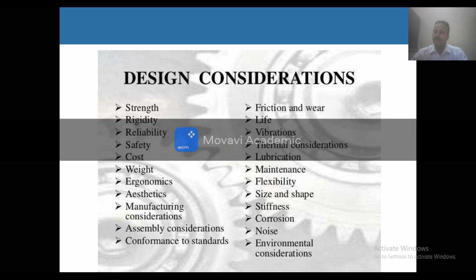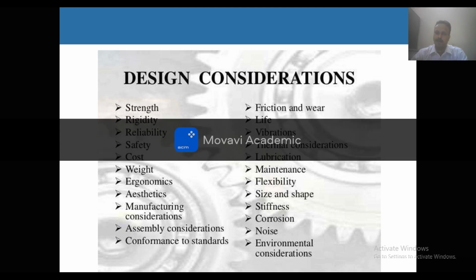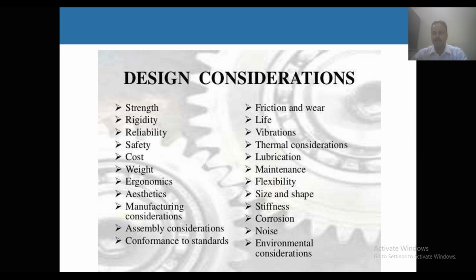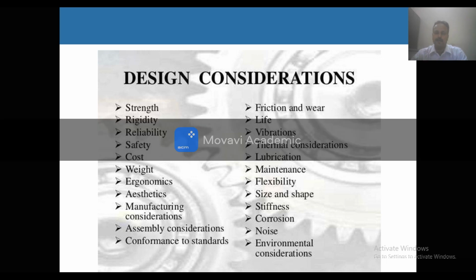If you are designing a ball for a ball bearing application, that ball bearing will be subjected to semi-solid or solid lubricant. It will generally not be subjected to liquid lubricant. So we need to see the acceptability of those balls for semi-solid and solid lubricants.